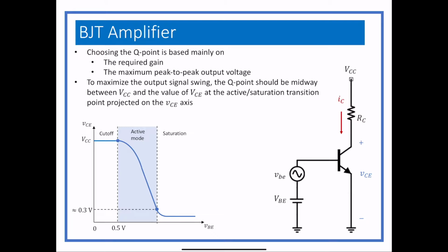So if we had a VCC of 20, we would not generally be able to get a VCE of exactly halfway between 20 minus 0.3, but we would try to get it to be about 10 if we could, depending on the design. You try to get it to the half point, and sometimes you can, and most of the time it's a very general area.